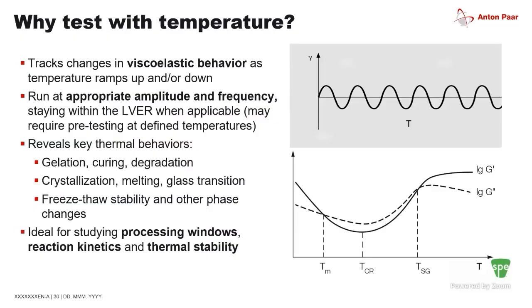Now, what we can also do, outside of just looking at these from an isothermal response, is look at the material behavior as a function of different temperatures. The reason that's important is that if you're processing the material, or if the sample has to go through different temperature conditions, it gives us an idea about reaction kinetics or thermal stability, as well as the processing window.